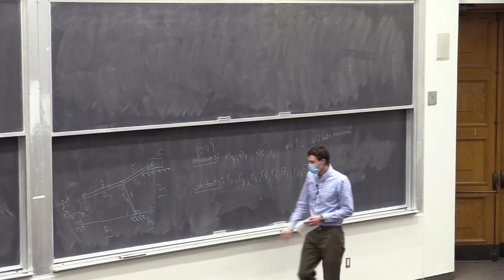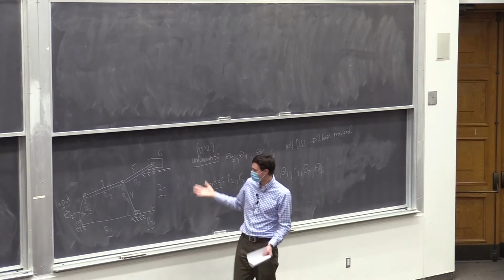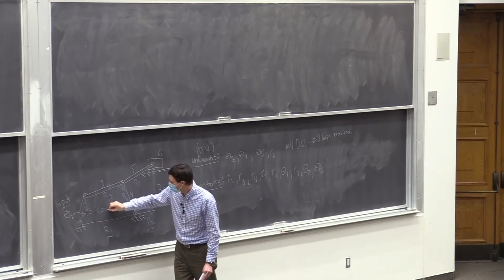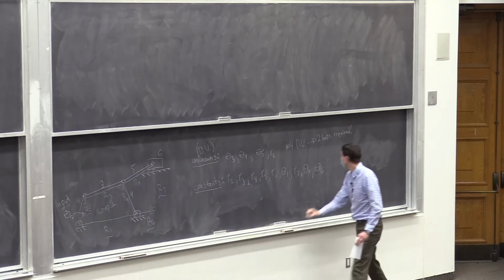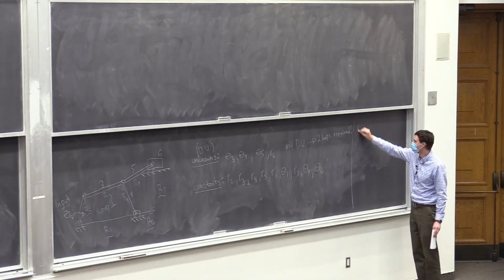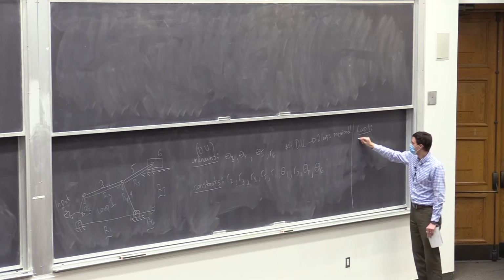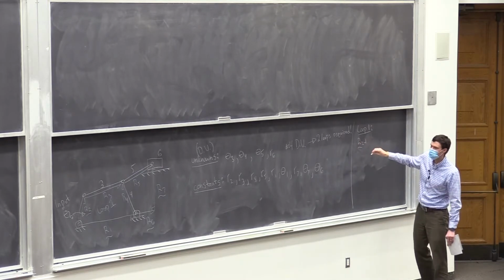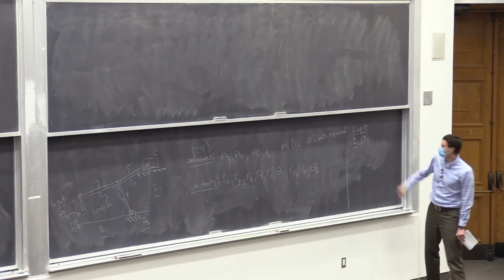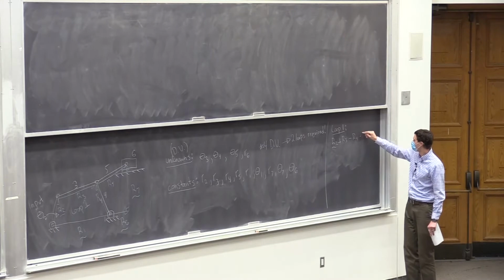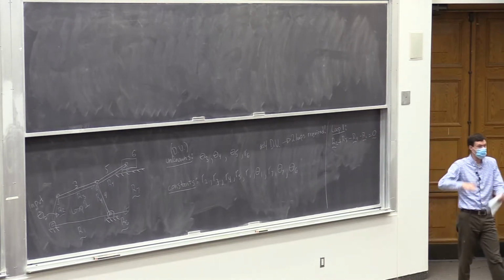But if we design 2 loops, and I think it's pretty clear what a logical loop would be. Loop 1 would be this, the 4 bar. So let's write out the equation here. 2 plus 3 minus 4 minus 1. So there's our first loop, and that's just a 4 bar.